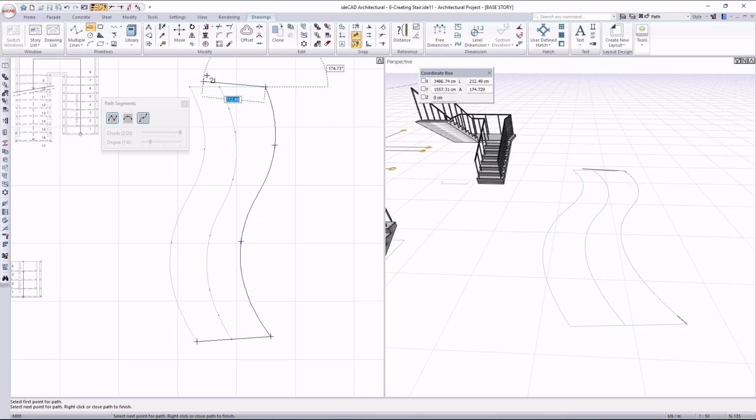Then, switch the path type back to straight and draw the straight edge. Next, switch to curved and continue drawing the curved edge. Clicking the last point automatically ends the command. There's no need to right-click again. Next, draw the line of travel. With the curved route type selected, click the necessary points to define the path. Right-click to complete the drawing.